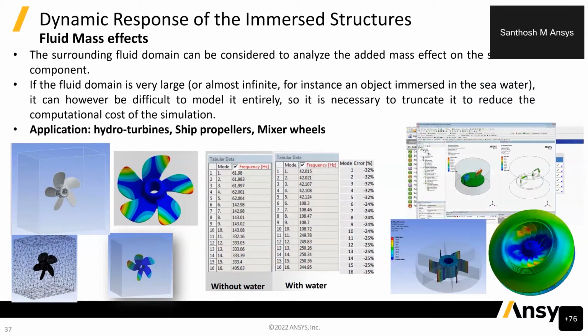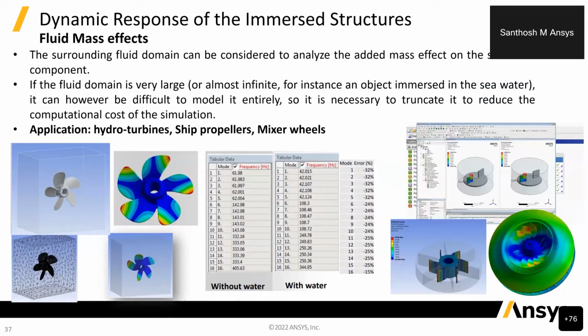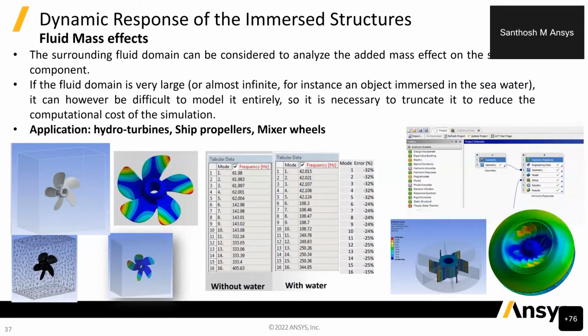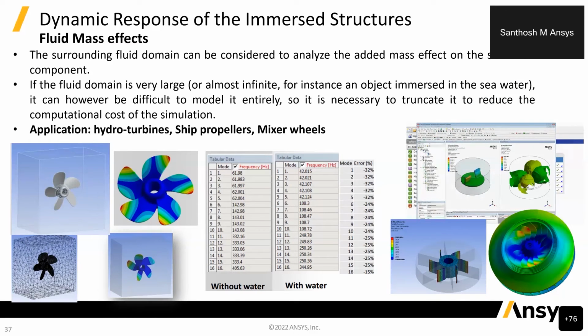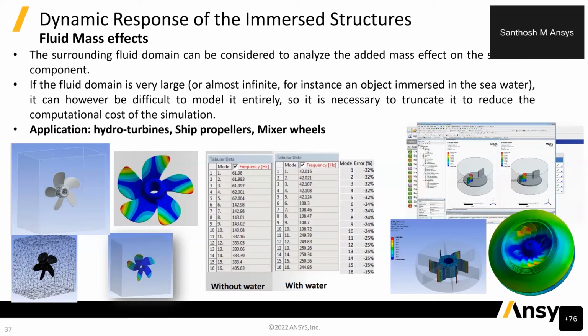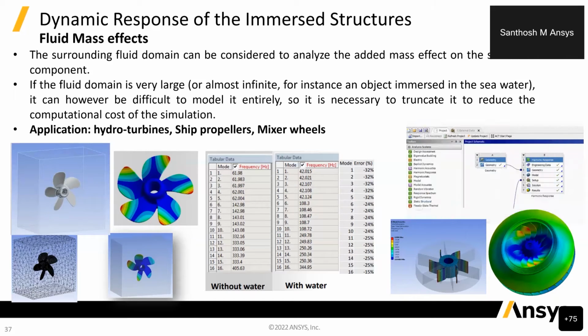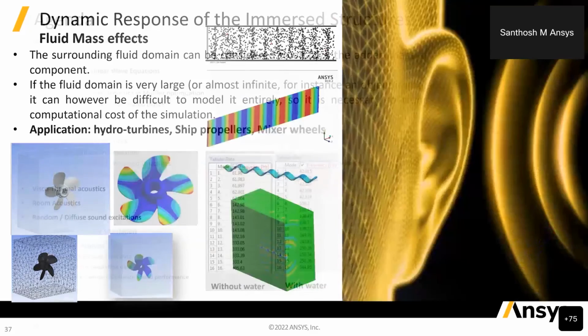And in industry, especially for underwater applications, when we have any impeller or ship turbines which are inside the water, their wet natural frequencies are much lower compared to when we test those propellers in a lab in an air environment, because the water is heavy, which adds some extra mass to the structure. So the same vibroacoustic technique can be used to study the wet frequencies of the structure, which are partially or fully immersed inside the water or any heavy fluid, right?